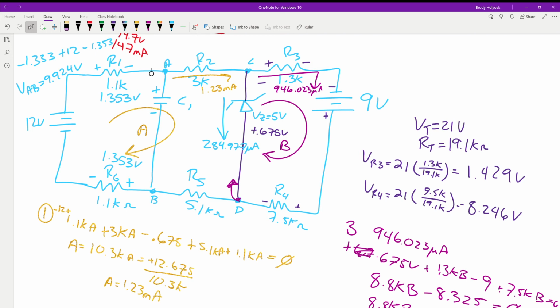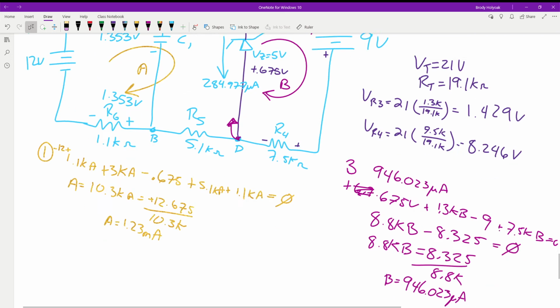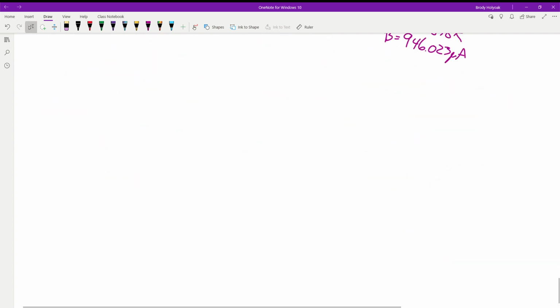Okay. Any questions about these? What were the basic steps? The capacitor's open, take out the diode, Thevenize it. Basically, Thevenize the diode, find out what the voltage is across there to determine if it's forward or reverse, and polarity. Like I said, what we just did was Thevenin. We just didn't go through all the major steps because we're not going to be swapping this in and out. We just wanted to know one voltage.